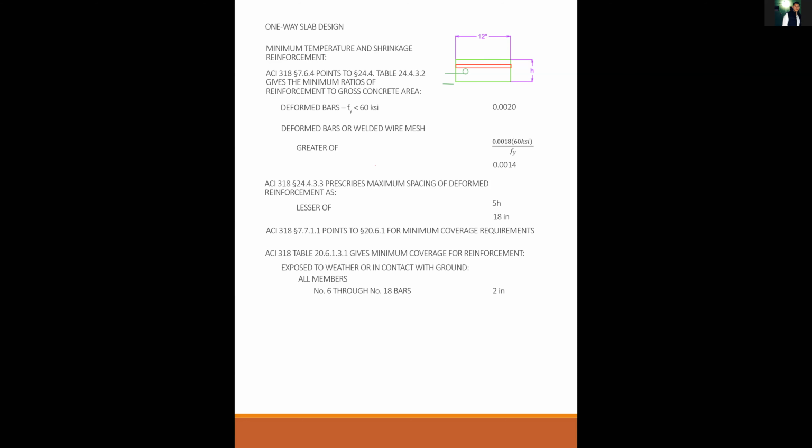Professor, I have a question. For the spacing of the bars, do both directions have to be spaced the same? No. But both directions need to be less than the maximum. Usually one direction will have a different spacing than the other. Okay. From what I see in the picture of the slab, one way is longer than the other, right? It is.